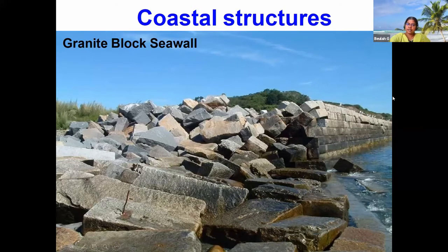Here, this type of seawall is constructed by piling up the blocks one over the other, naturally without any interlocking system. This has collapsed mainly because there was no interlocking between one stone and another stone. That's why it has failed.